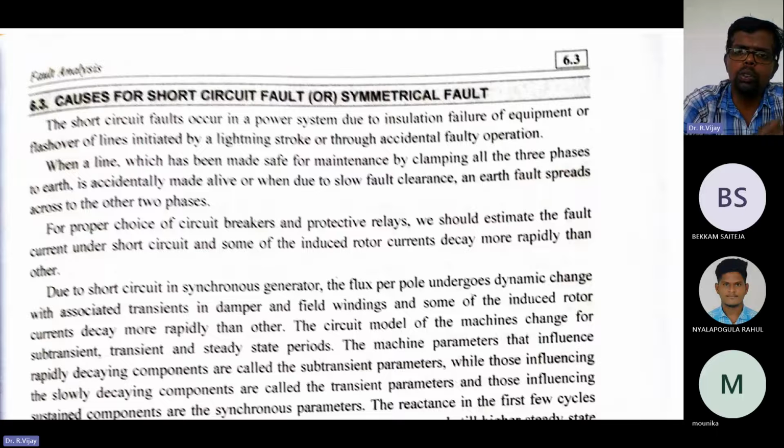Okay, it will boil due to full load. Transformer oil will boil like an egg, because you need to replace the transformer oil and test the viscosity. If the viscosity is not there, then simply the transformer will boil. Like how we heat water, the transformer oil also will be boiled, and sometimes it will flash over. That oil will flash over, it will come out.